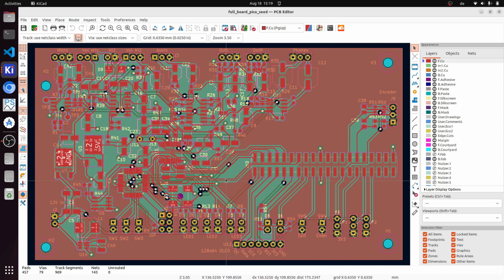Here you see this 40-pin connector, which then accepts an adapter board to either connect to a Raspberry Pi Pico or Electrosmith Daisy Seed. Regarding layers, I thought for a long time whether I should try to build this board using just 2 layers or more. The advantage of 2 layers is that it's still debuggable, it's still correctable, but I found out that it's pretty difficult to build, and also I would need to split ground planes quite a bit, and I've heard or read that this might also cause problems.